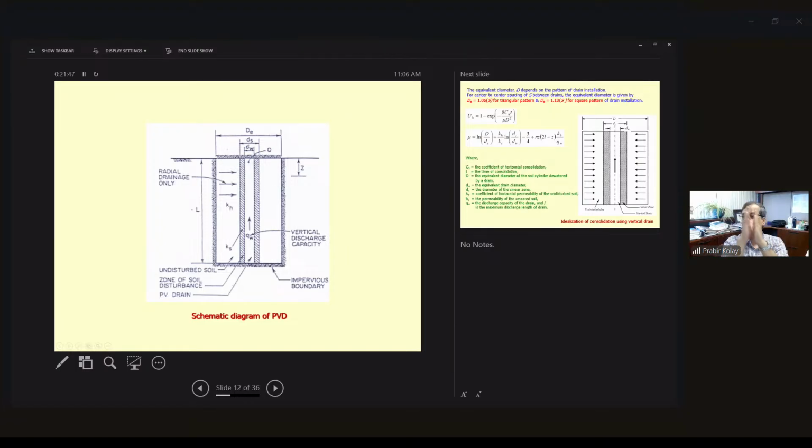Inside there is a core with different patterns, made of a high density polyethylene type of material. The top portion is covered with geosynthetic material, so that when water goes through the geosynthetic material, only the water comes through, no soil particles. And it comes in a roll, so it is easy to install compared to the sand drain. That's the advantage. We will talk about that.